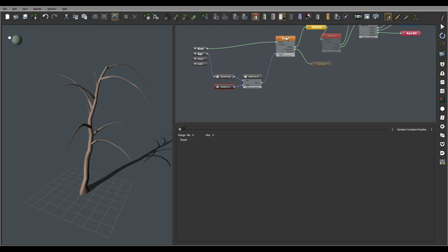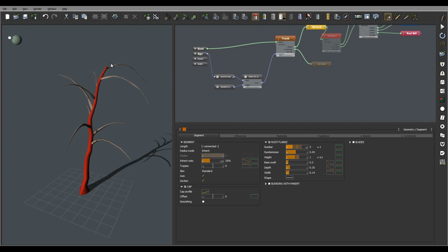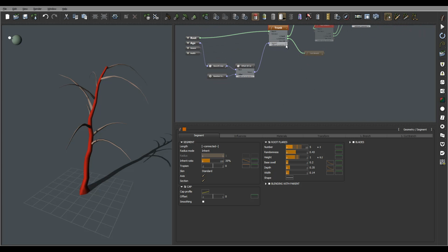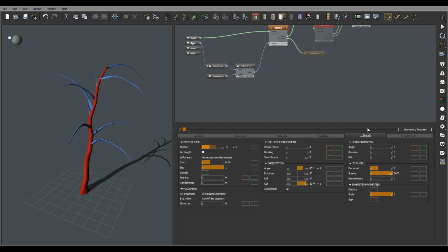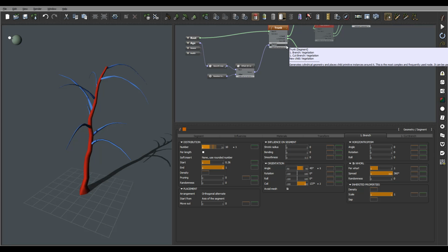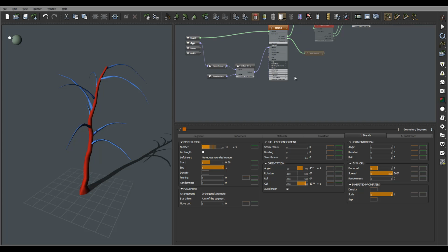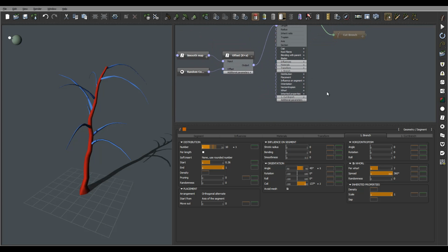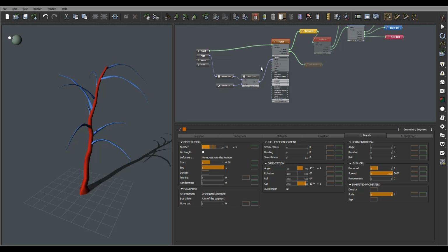The next, for example, if we look right here, I have the different branches. I want to control those branches, how many I'm producing. So let me go ahead, click on a branch, and I'm going to expand right here. Okay, we'll expand the branches as well. So for example, I want to take these branches and control them based on the health, or maybe even age, whatever you prefer. For example, when it's smaller, I want to have few branches, and as it grows up, have more branches, like a branch is growing. Besides, we can also control the branch length at this time.